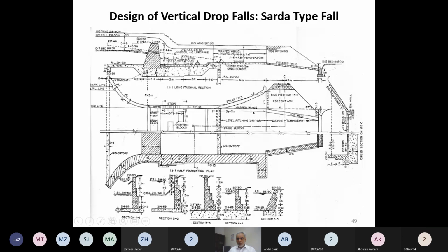So when we have to provide a canal fall, we give a transition to the banks with the help of the wing wall. This wall we call the wing wall. We give a change to the sides of the canal in such a way that when it reaches the crest, it becomes simply a rectangular channel. So here its shape will become rectangular.